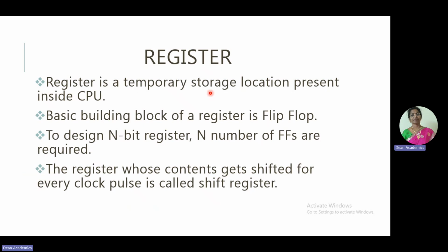A register is a temporary storage location present inside a CPU. The basic building block of a register is the flip-flop. You can use any type of flip-flop, but here we are going to implement it with a D flip-flop. To design an n-bit register, we need n flip-flops. And then we can design a shift register.